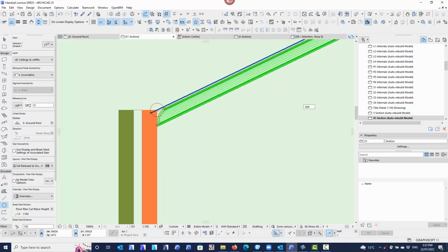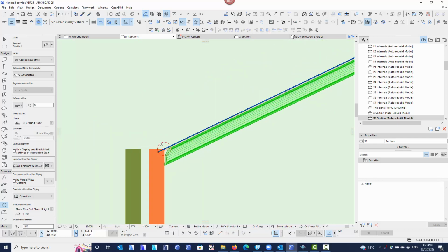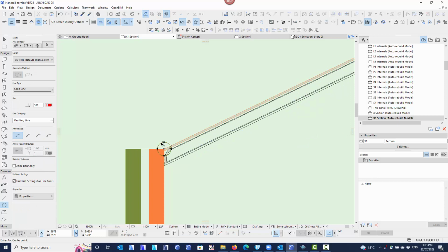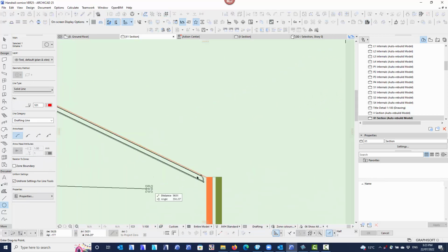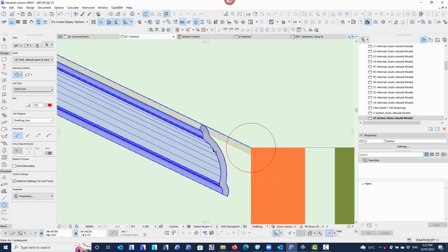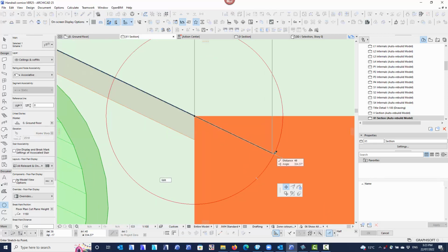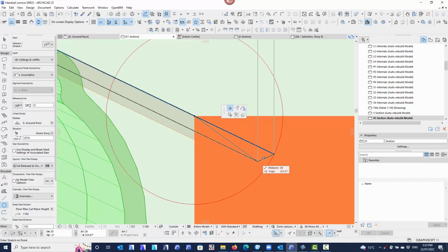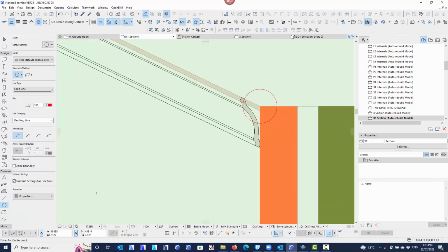And because it's all linked together, it's all one railing, the whole thing has moved. So all I need to do now is to grab that circle and drag a copy of it to the other side to where I know the node is. Grab my ceiling, grab that node, stretch, follow the guideline, I'll zoom in a bit, follow that guideline to where it meets and intersects with the circle, grab the second node and drag that down, and Bob's your uncle, it's now in place.